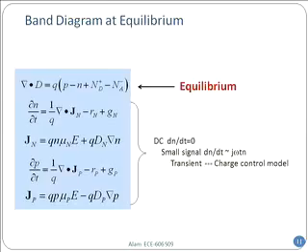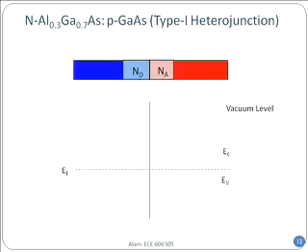So let's solve the Poisson equation by this graphical method, and that's the band diagram. And the rules are exactly the same. I cannot remind you too many times that you draw the Fermi level. One side is N, the larger band gap side, let's say the emitter is N. So you put the larger band gap side as N, and let's say for this particular case, aluminum gallium arsenide, this is 1.8 eV. You will put the vacuum level with chi 1.